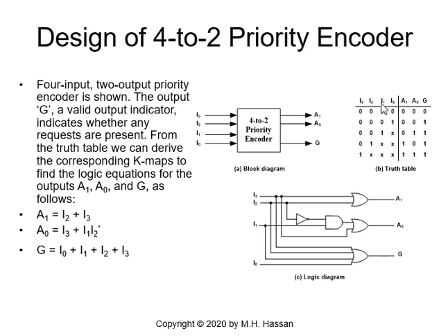Once I1 becomes 1, requesting a service, whether I0 is requesting a service or not, the output of the encoder will be 0, 1, which is equivalent to 1, representing device I1. Deliberately, I use I to indicate an input interrupting device.